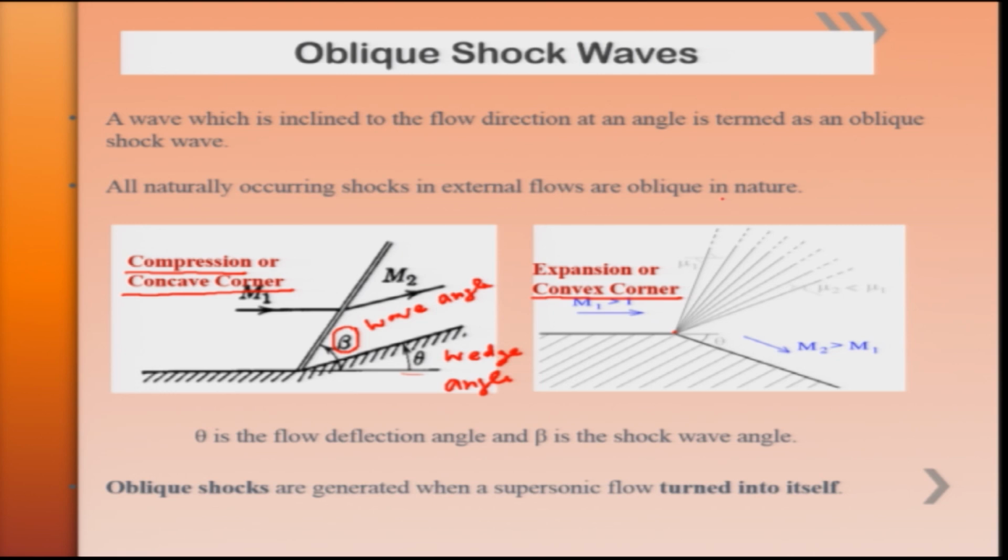That is the property of an expansion fan: it relaxes the flow, that is, the static properties relax, however the Mach number increases, whereas in the counterpart, the oblique shock wave, the flow properties jump, whereas the Mach number decreases. So shock and expansion fans are two opposite phenomena which take place in supersonic flows.